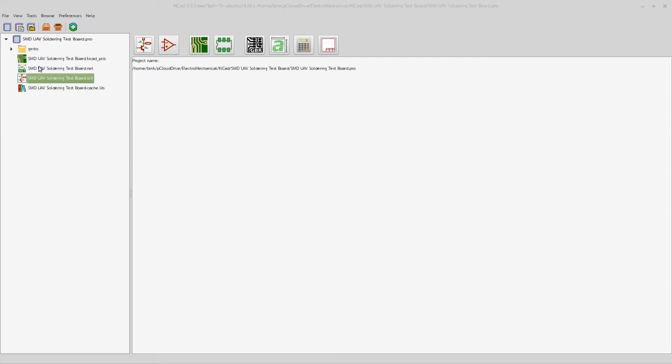What I want to show you here, this is your schematic. So this is the logical symbol that you use when you're creating, and by logical I mean pretend, right? The thing that represents the actual item. And then up here, this one that I'm clicking on now, this is the actual circuit board itself. This is where you define the actual shape of the part that's going to go on there, and the pitch of the pins, how far apart they are from each other, and actually start placing them around the board. So I'll quickly show you a look at both.